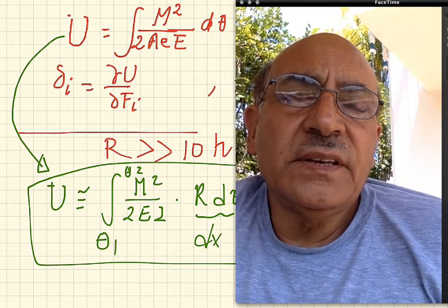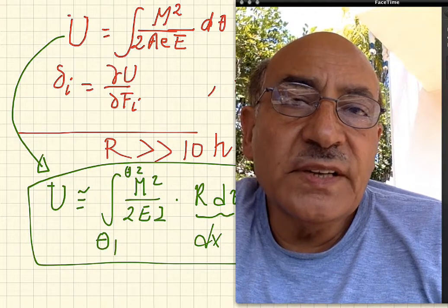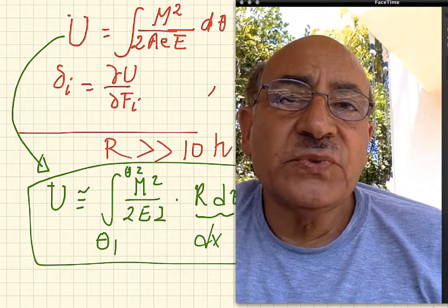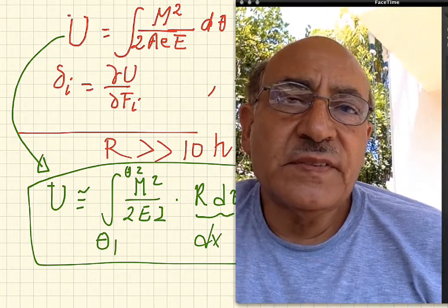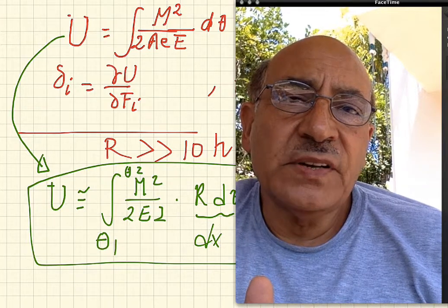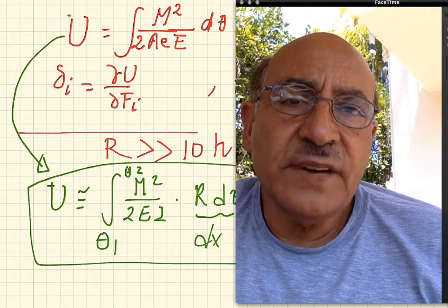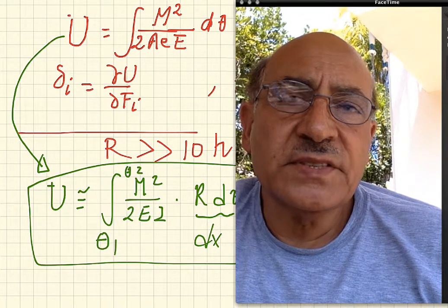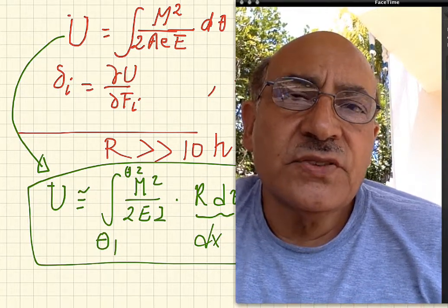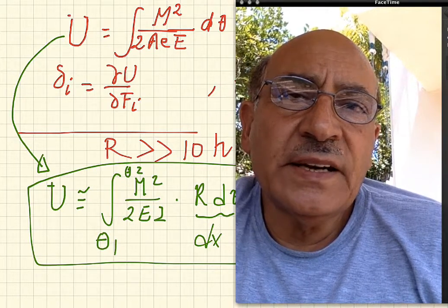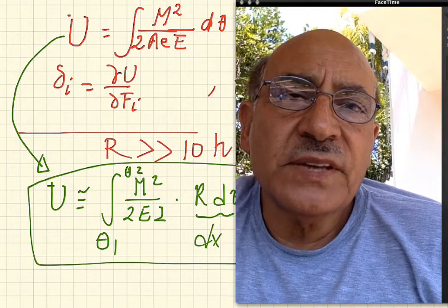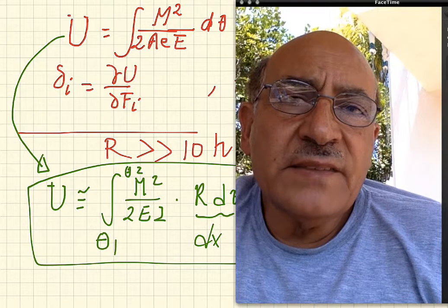Generally, we don't compute the energy completely and take the derivatives, but we exchange the derivative operator with the integral operator, and then take the derivative inside the integral. It is easier than finding the final result first and then differentiating it. So in this case, we can find deflections or rotation. So that's kind of the theory behind it.